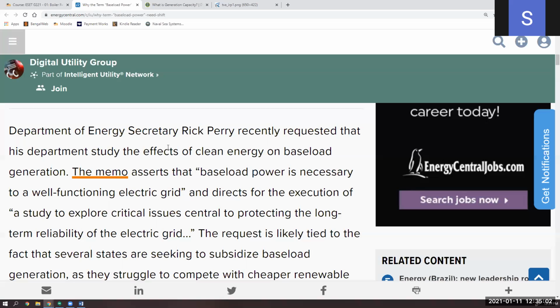So when we're using these energy sources, we've got these steam plants, whether they're nuclear or coal, we look at how often they produce their maximum energy, and that's how we get our capacity factor, right? So if you are able to produce 100% of your energy 70% of the time, your capacity factor is 70%. If you can produce 50% of your energy 100% of the time, the capacity factor is 50%, right? So how often you can produce 100% power.